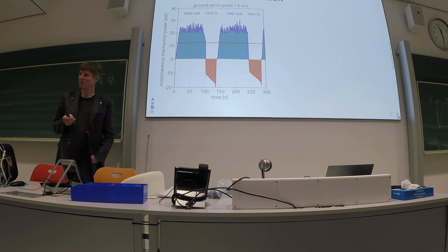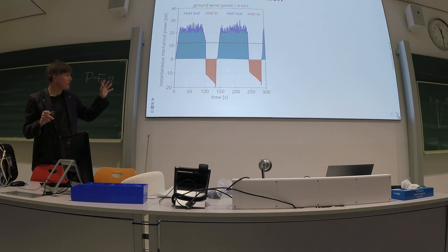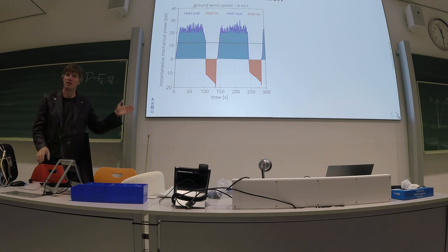Yes? Due to the steering, your lift vector is not perfectly aligned with the tether, reducing the efficiency of the power generation. So basically, because you're flying figure eights, in the center you'll have a high peak, while on the turns you're also less aligned with the wind, so that also plays a part. It's also turning, so you're generating less. Yeah, from what I see, the last point is the most important point, the misalignment of the tether.